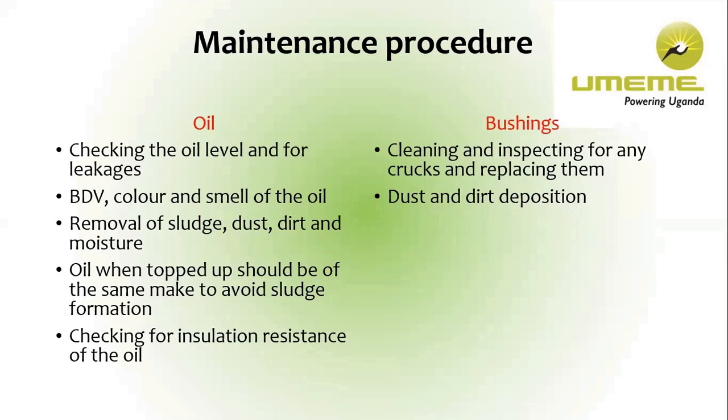So this oil is always inspected. You check for oil level and for any leakages. The moment that tank has any leakage, it means that moisture can enter. The moment water enters the oil, it can reduce its insulating properties.